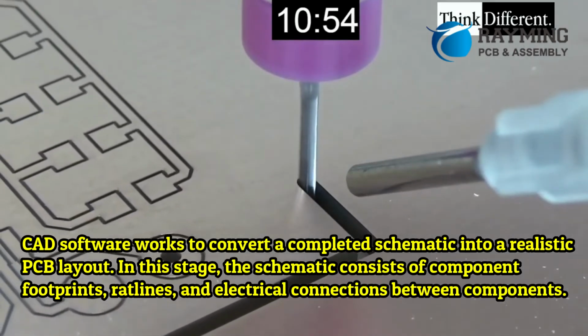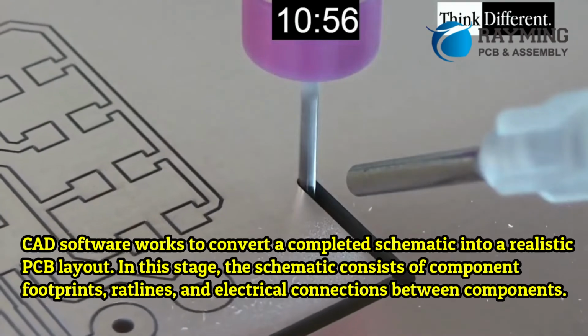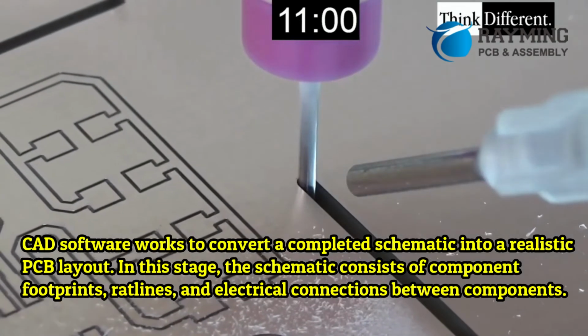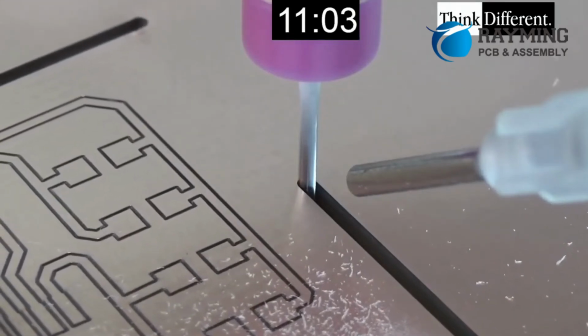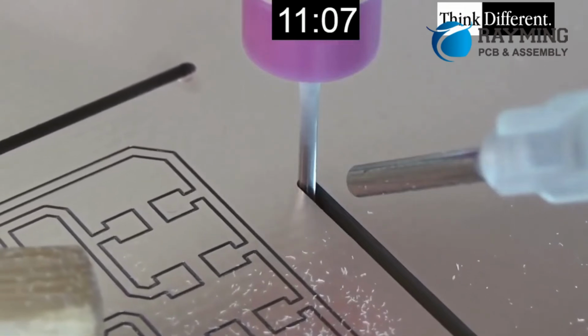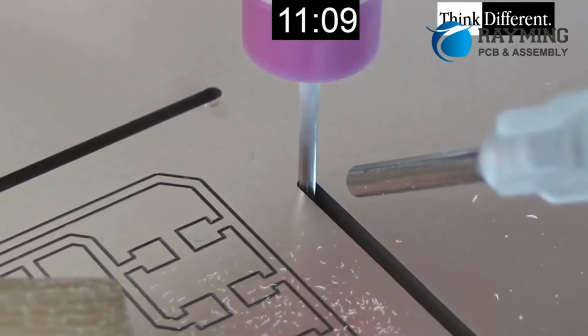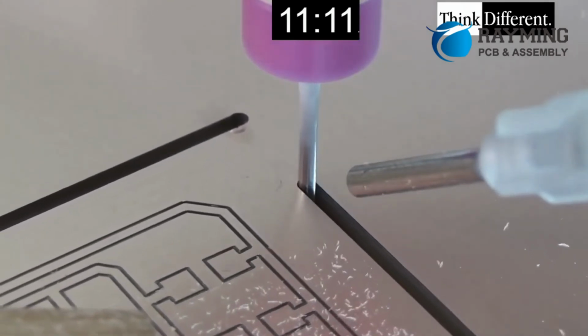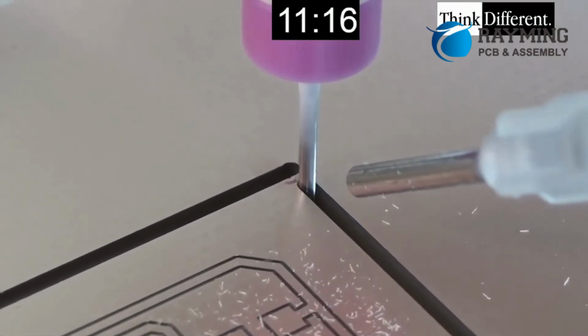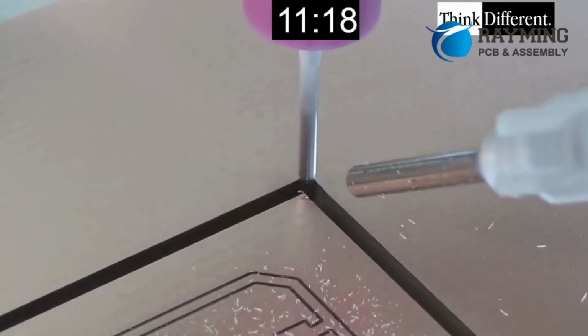In this stage, the schematic consists of component footprints, rat lines, and electrical connections between components. A designer then arranges these components and utilizes the rat lines to draw traces, vias, and copper pours. We identify a via as a small through-hole carrying an electrical connection to another layer of the PCB. It may also serve as a thermal via that connects to an internal ground plane.